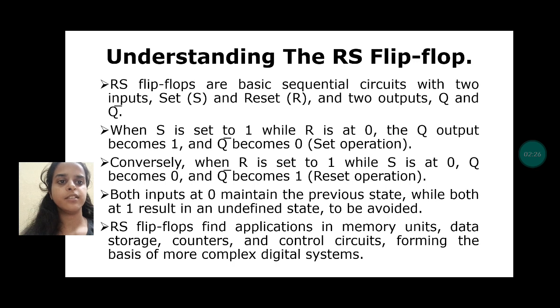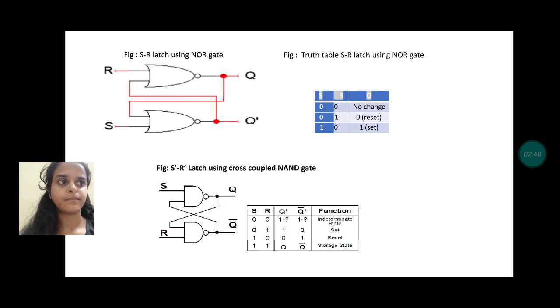Both inputs at 0 maintain the previous state, while both at 1 result in an undefined state to be avoided. RS flip-flops find applications in memory units, data storage, counters, and control circuits, forming the basis of more complex digital systems.